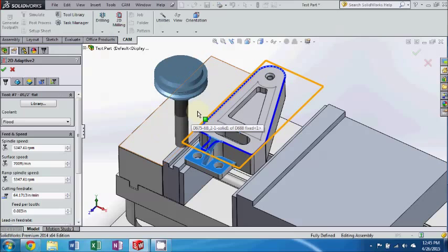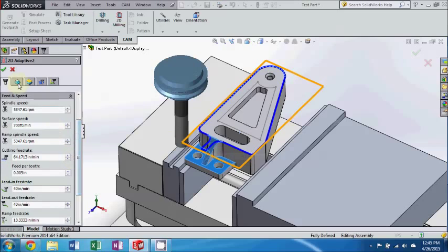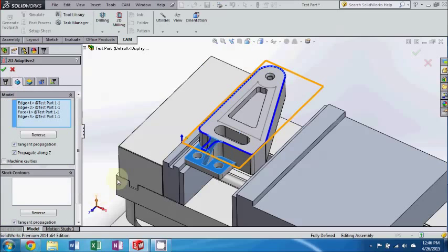Just like before with any process, you have to pick a tool type. We picked this 1/2 inch end mill here to do the job, so you can make it inside of these radii right here. And it's the usual selection process. I'm just going to burn through that since we've already touched on it. Okay, so moving on to the selection process.